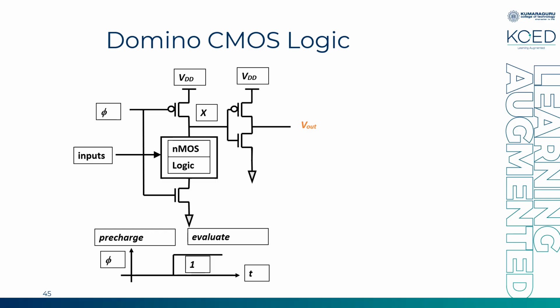For dynamic CMOS, you will have false input being fed to the fan out gates. If you look at the actual working of dynamic CMOS, pre-charge and evaluation keep going on. In one evaluation, you force one set of inputs and get the output. Before forcing the next set of inputs, you have to pre-charge it. So your sequence of working will go like pre-charge, evaluation.